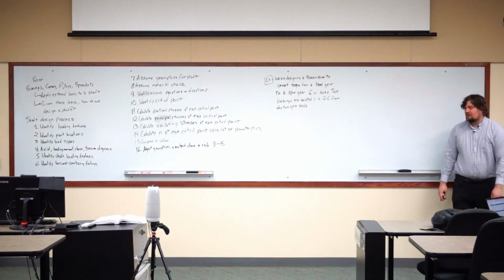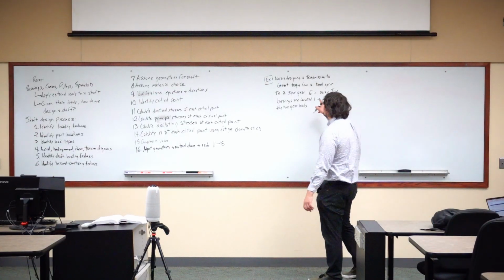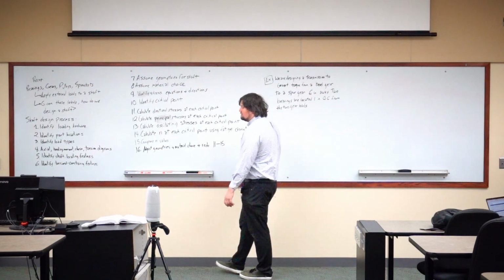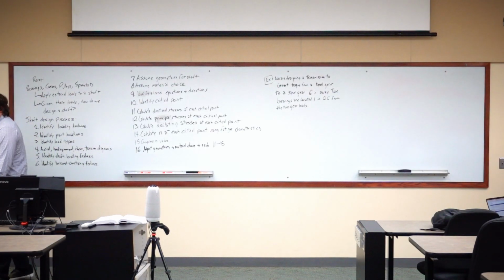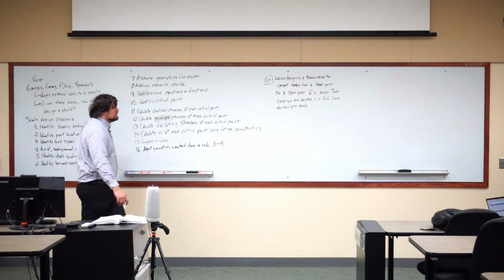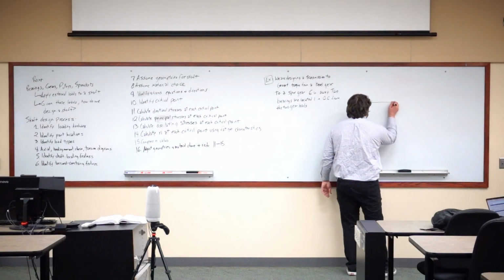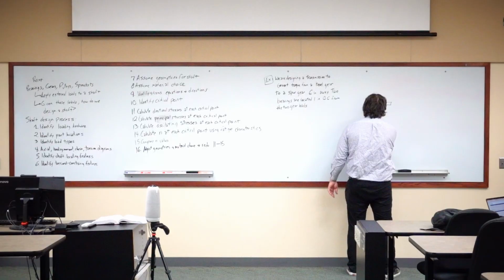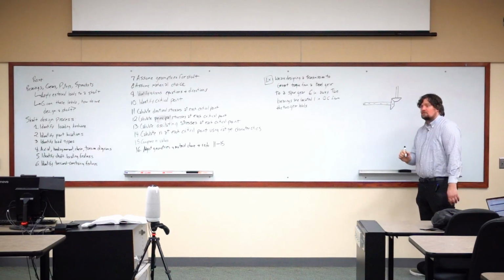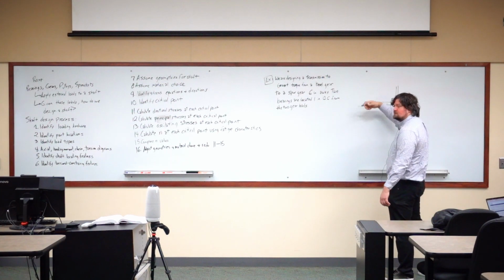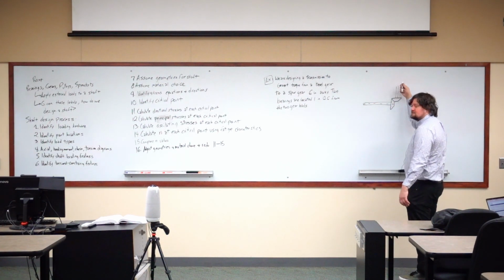So here's what we have. In a basic diagram, we're designing a transmission to convert torque from a bevel gear to a spur gear located 6 inches away. We haven't talked about gears yet. A bevel gear usually acts at a 90-degree angle. So if I have one shaft rotating along this axis, and I have another shaft rotating along this axis, oftentimes they will have a bevel gear between them, and the bevel gear meshes like this. Okay? And so this allows this shaft to rotate in this direction, and then this shaft rotates in that direction.